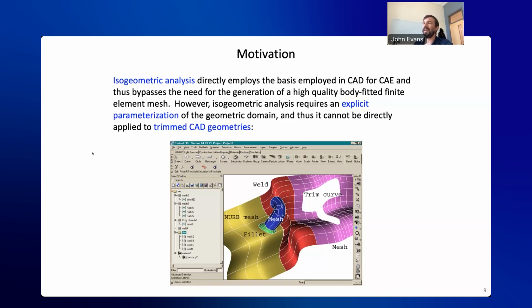So you need to actually do some volume parameterization or meshing anyways when working with a B-rep if you actually need to conduct a volumetric finite element analysis or isogeometric analysis, what have you, as is required for analyzing fluid flow, acoustics, electromagnetics, deformation of a solid